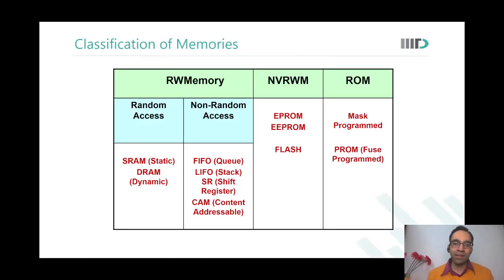And as you rightly said, DRAM is based on a one transistor cell, and due to this, it is much denser than an SRAM. For SRAM, we already saw in the previous class, and we will see in much more detail in this class, that the most commonly used cell is a 6 transistor cell. So 6 transistors mean some area, whereas DRAM, if it is just one transistor and one capacitor, since it's just one transistor, it's denser. And with memories, area is diamond. So DRAMs are very important.